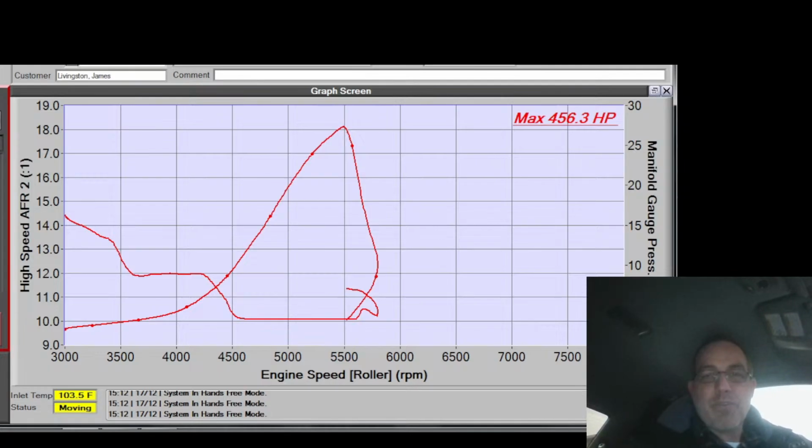And it's doing that at 28%. What the fuck? It's doing it at 5%. So at 5% wastegate duty, we've got 30 pounds of boost. Well, that's not going to work, is it? Goddamn it.